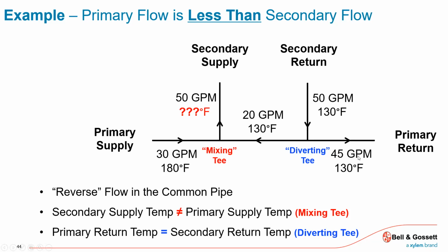And it's October, November, and it's 42 degrees out. I'm in a reset schedule. All I need is 140 degree water. Perfect. And then that will change as October becomes December, becomes February. All of a sudden, maybe I need more of my plant. More of that flow is being injected to get that design 160, 180, 190, whatever I need on that really cold day. That's what's happening in all of these connections.